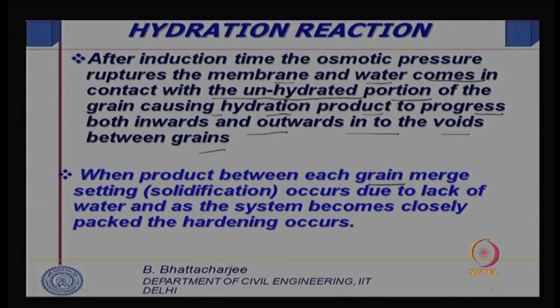Further, the process of more generation of solids might take place, more hydration product may form and fill in all the voids that are available within the space, right. So, when product between each grain merges, setting occurs due to lack of water as the system becomes closely packed, and then hardening would occur.